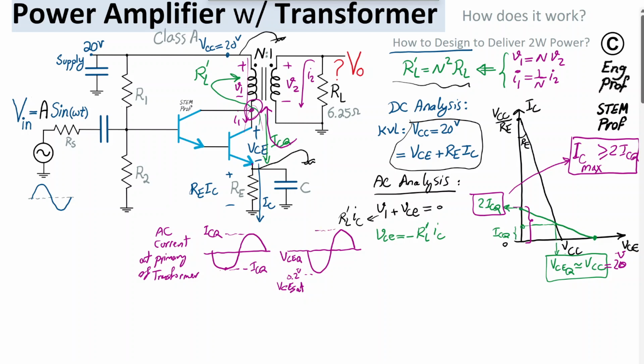And then on top, let's make the assumption that this is practically 0 given the size of the 20 volt supply, or VCC. On the other side, we go 20 volt down, we go 20 volt up. So effectively the center is 20, so we have up to 40 volt max VCE that can happen for the transistor.